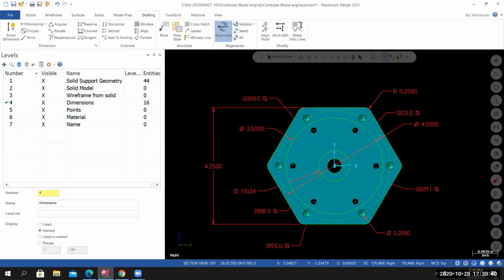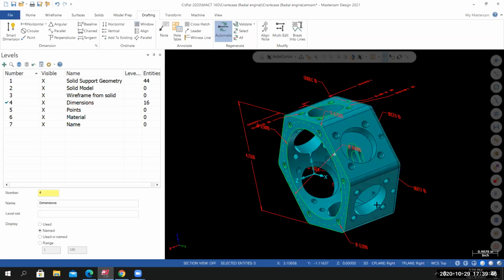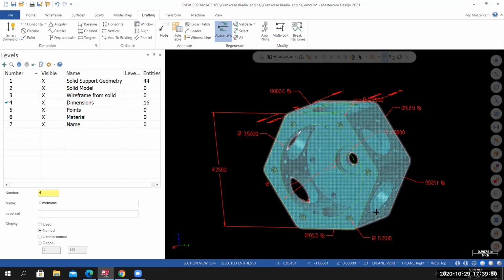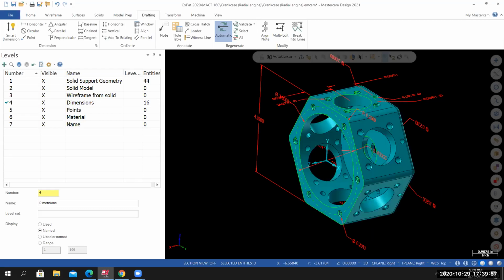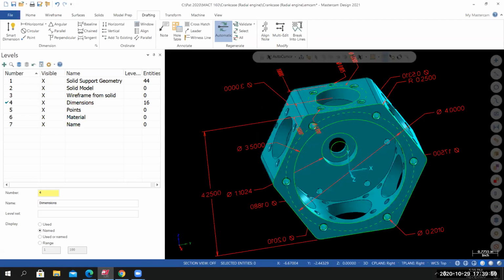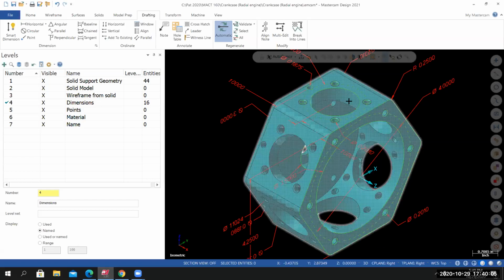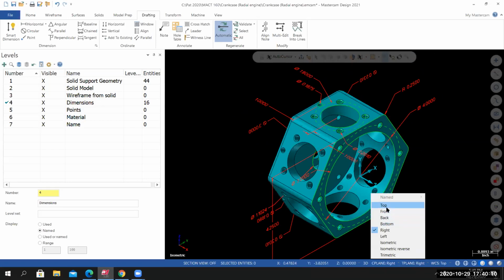So far everything has checked out. The only thing that I really haven't dimensioned would be the thickness, the depth of this pocket, and then the depth of this pocket. We can try and do that. We'll see what happens. If I look at it from a default isometric view, the back plane is the one that I'm going to want to activate. Actually, let's do the front plane. Make the C plane the front.